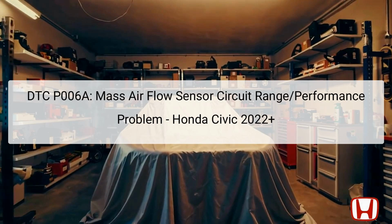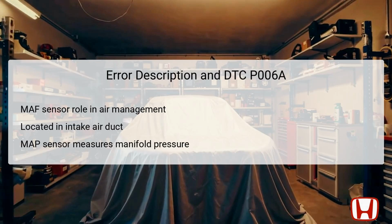and addressing underlying issues. The DTC P006A pertains to the performance of the mass airflow MAF sensor, which is critical for calculating the correct air-fuel mixture essential for combustion in the engine. This sensor is positioned in the intake air duct post-air cleaner, ensuring the air entering the engine is accurately measured. The MAP sensor also plays a significant role by measuring the pressure in the intake manifold, further assisting in determining